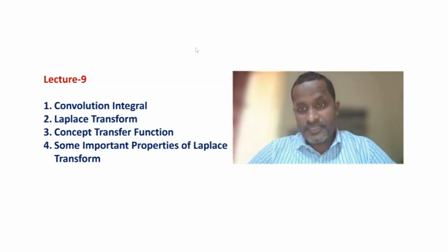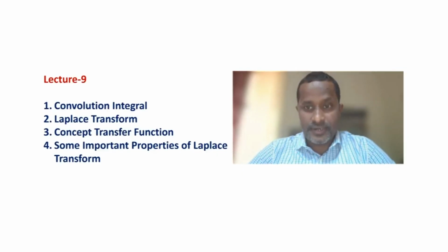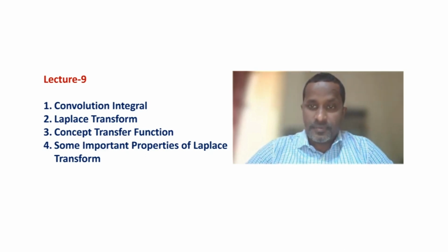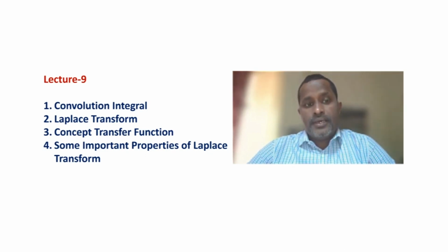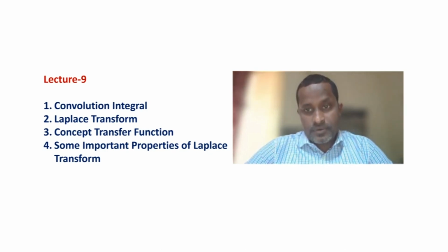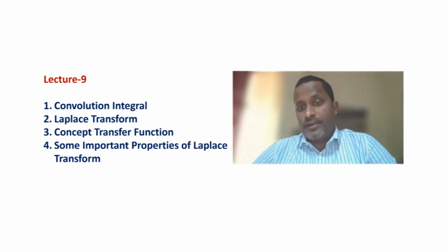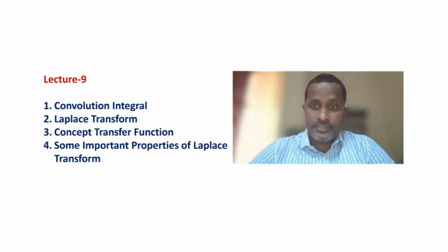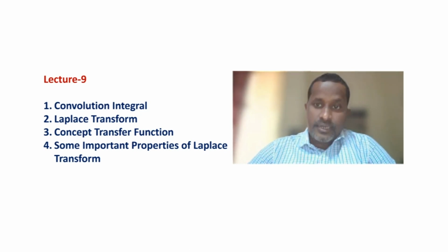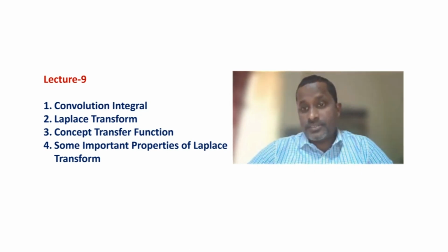In this lecture, we will be discussing the concept of convolution integral from the concept of convolution sum. Then we'll apply Laplace transform on this convolution integral and find the linear relationship between input and output. From this linear relationship, we'll find the transfer function concept, which will relate input and output.